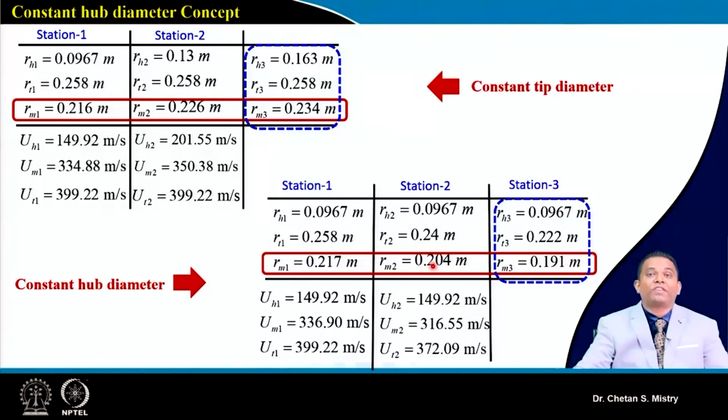And if we have this different configuration, we can say the observation parameters like diffusion factor, degree of reaction, de Haller's factor, my deflection angle, my different flow angles, all of those will be getting changed, or will have different values. There is a purpose why one lecture is dedicated specifically to this particular design, because it will give us the feeling of what happens if we configure this kind of design. Okay, so let's move on with what we are discussing.